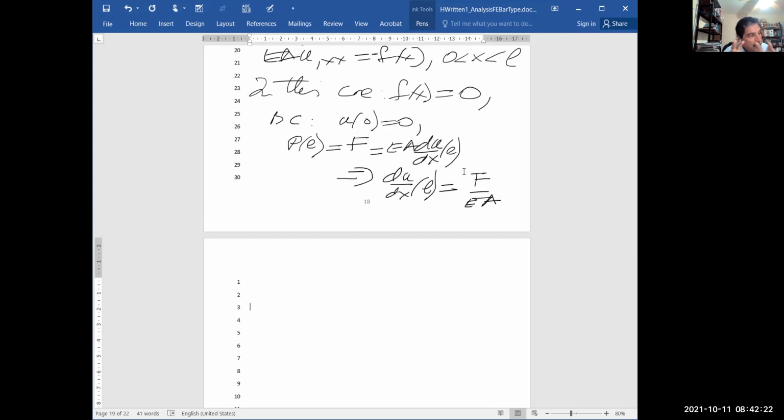So first, you solve it for the unknown displacements. After you solve that first subsystem, you have all joint displacements as known. So the next step is to find the unknown external forces.